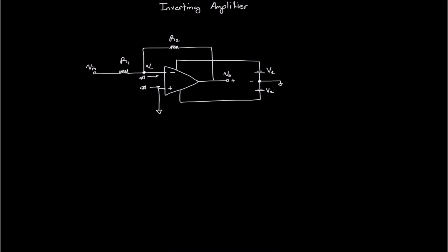So we can then go ahead and determine our gain. We can first determine V out, and then we can determine our gain for the amplifier. First thing we look at is that we can use superposition, or we could use the node voltage method. Superposition is simpler, so let's go with superposition. With superposition, for V minus 1, let's set V out equal to 0.